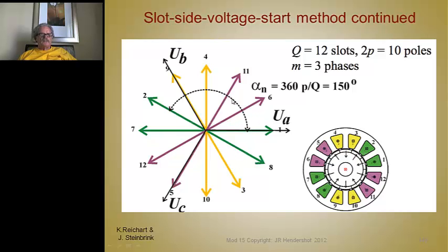1, 2, 3, 4, 5. Now that's how you number slot 4 that we're going to see over here. Count 1, 2, 3, 4, 5. Here's the first slot, which is slot 5. That's the first slot where phase C goes. And so on. You keep going around till you have all these slots numbered. And remember, we've color-coded here phase A, phase B, and phase C. So you color-code them here.